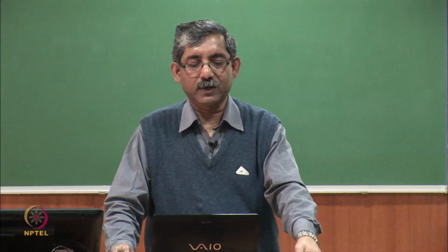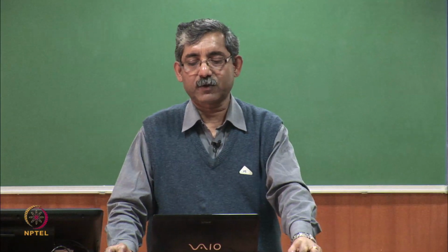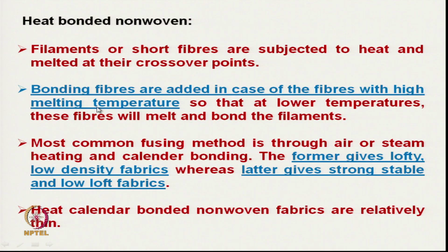So, bonding fibers are added in the case of fibers with high melting temperature, so that at a lower temperature these fibers will melt and bond the filaments.